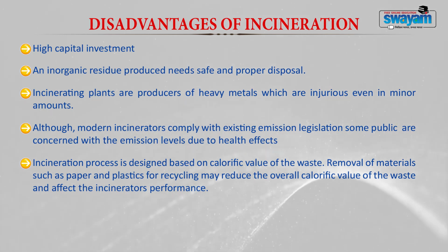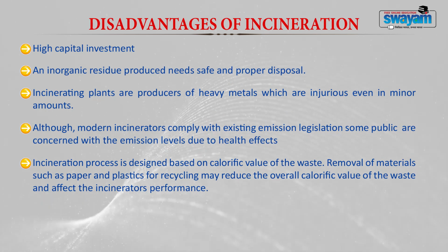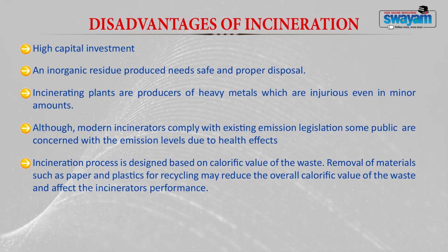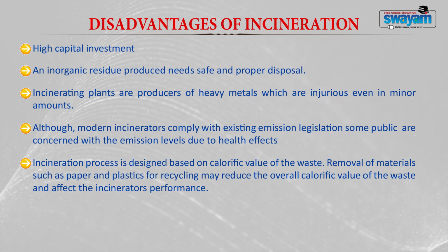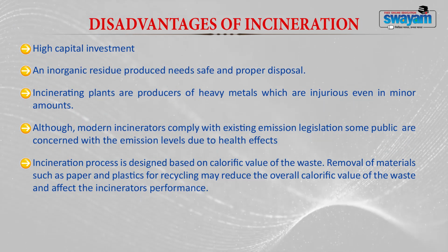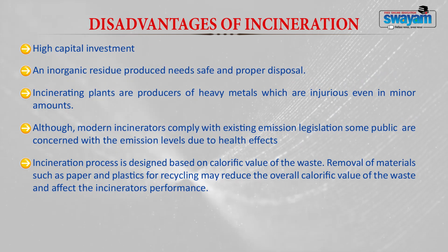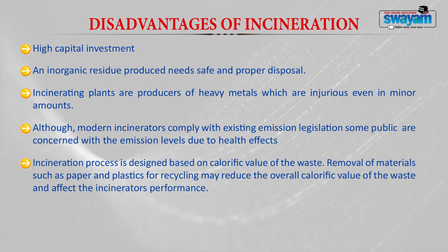Now, the calorific value is one which is going to generate heat, and with this heat you are going to convert it into electricity. Now, when you recover these materials like paper and plastic, the overall calorific value of the waste will get reduced. Once it gets reduced, obviously the heat generation will be less, and the energy recovery from this waste will be minimized.